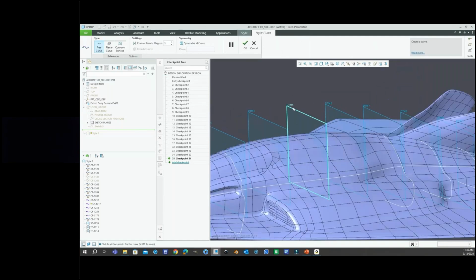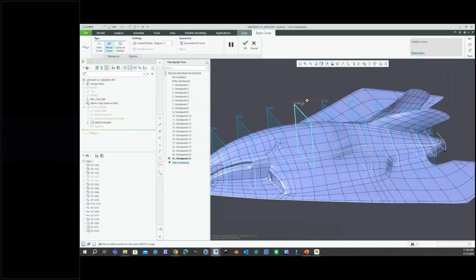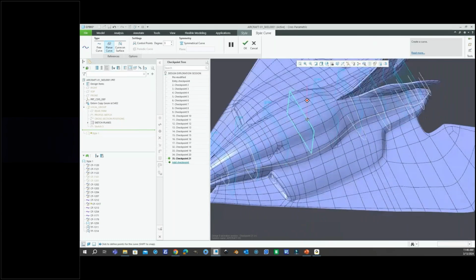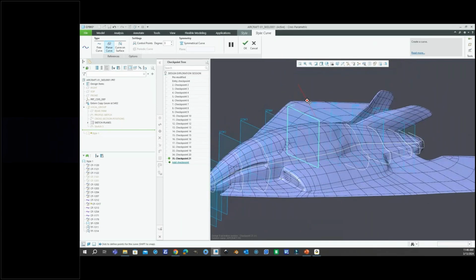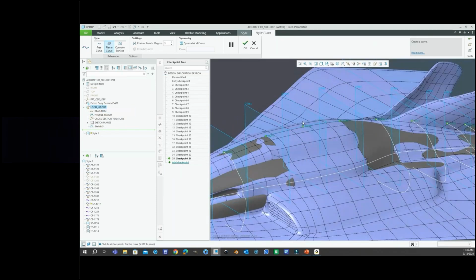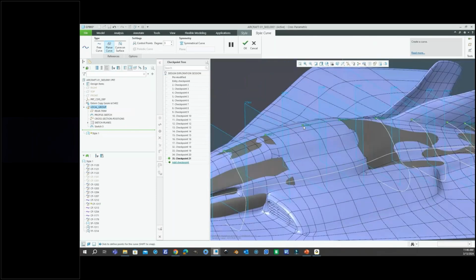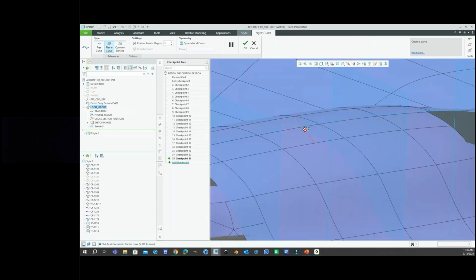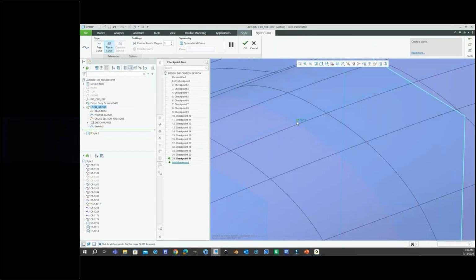All right. And I'm going to select planar curve, right? And that's going to ensure that the curve that I create is going to be on the plane. All right. Now I'm also going to need to see this blue curve, that profile curve that I sketched. And to snap to that curve, I have to hold Shift. We'll hold down Shift, left click, and then snap.